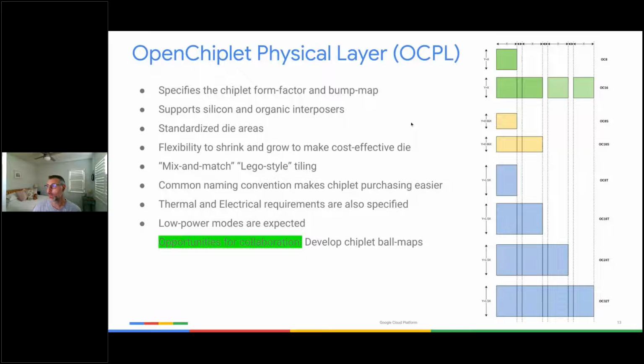If you think of PCI Express, it comes in by 4, by 8, by 16 widths. You could buy a by 8 PCI Express chip, but you want to buy 16. PCI Express is a pretty flexible standard, and you could potentially put down 2 by 8s next to each other to make the by 16 connection, or perhaps you procure a dedicated by 16 chiplet die.